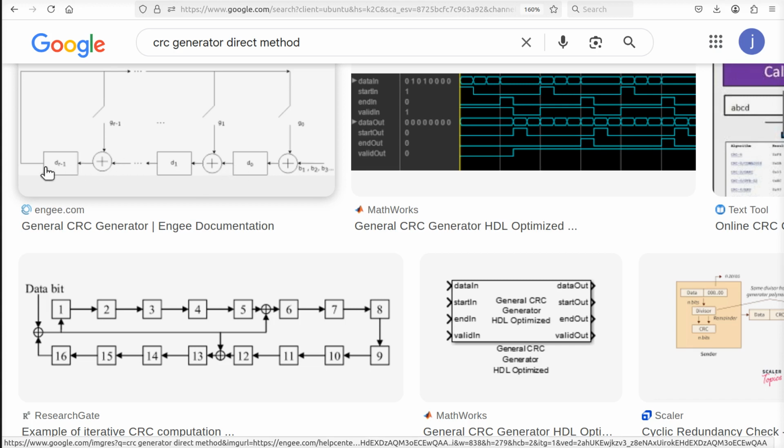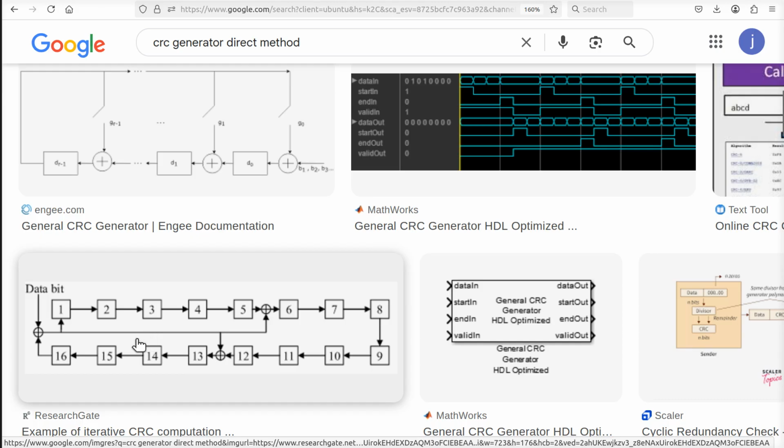So this is what's happening. If the most significant bit is a 1, when you shift left, those bits that hop to the left through the XOR will be inverted. And that control is solely based on the value coming out of the most significant bit of this shift register. Now let's look at this one. It's drawn in a terrible way, and it's shifting the other way, and it turns around and comes back the other way. I should have drawn these out by hand, but I didn't want to. I just wanted to put this video together. Bear with me here. Look what's happening.